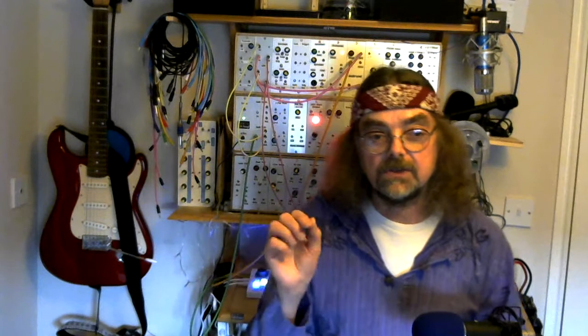The first one is a very simple op-amp VCO which produces a sawtooth wave and a pulse wave, and then the second part of the module uses a binary counter to provide sub-octave divisions of the original VCO output. But what it does, the Octivator takes the pulse wave output from the op-amp oscillator rather than the sawtooth wave.